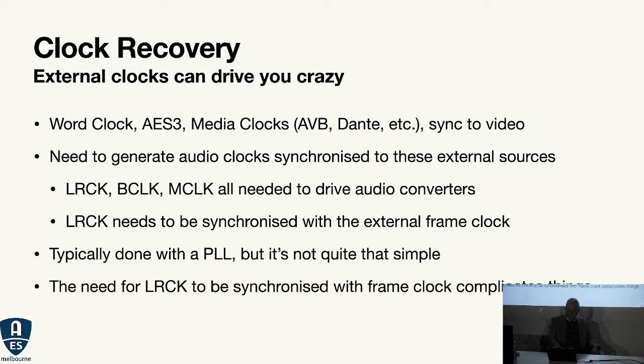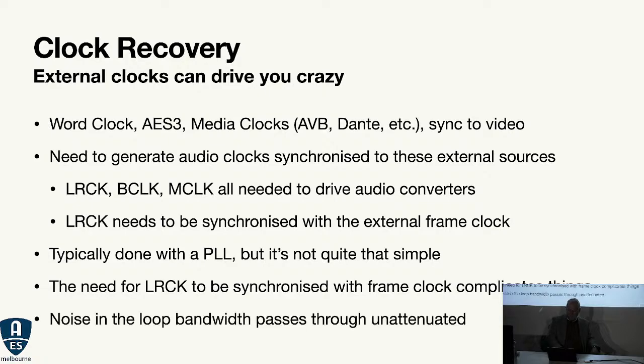It's not quite that easy, of course, because the LR clock, as I said, has to be synchronized to the frame sync. This makes things a little bit more difficult. And noise from your input can pass through the loop without being attenuated at all if that noise is inside the loop bandwidth. So these are little complications that you have to try and deal with.